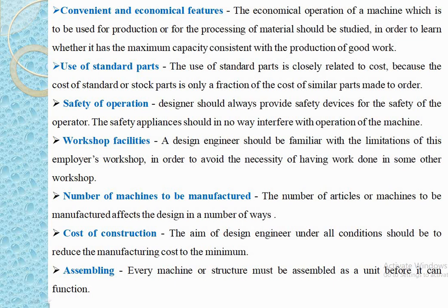That is most important. If you are assembling a particular machine or device at a particular location, and that location is at the farthest distance, and there are no transportation facilities available, then again it will add to the cost of the machine element. That's why the design engineer should take into account where we have to assemble the component and where the erection of that assembly will take place.